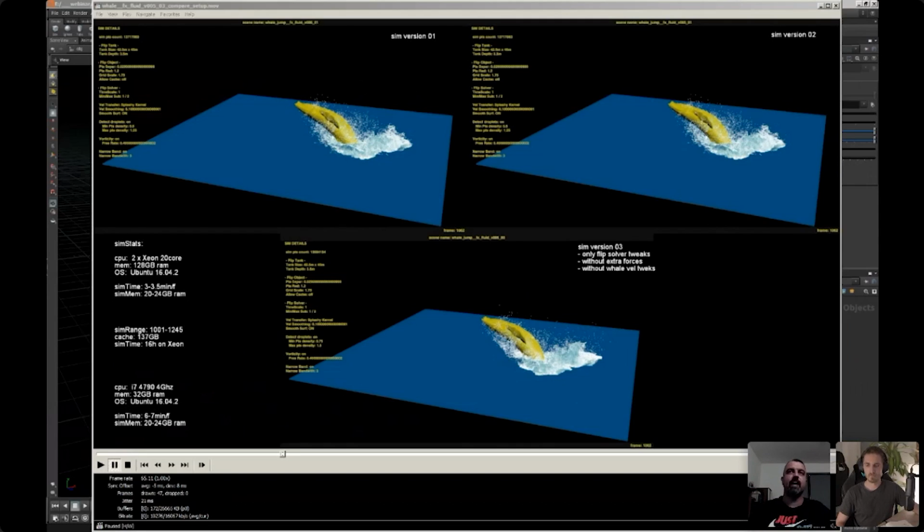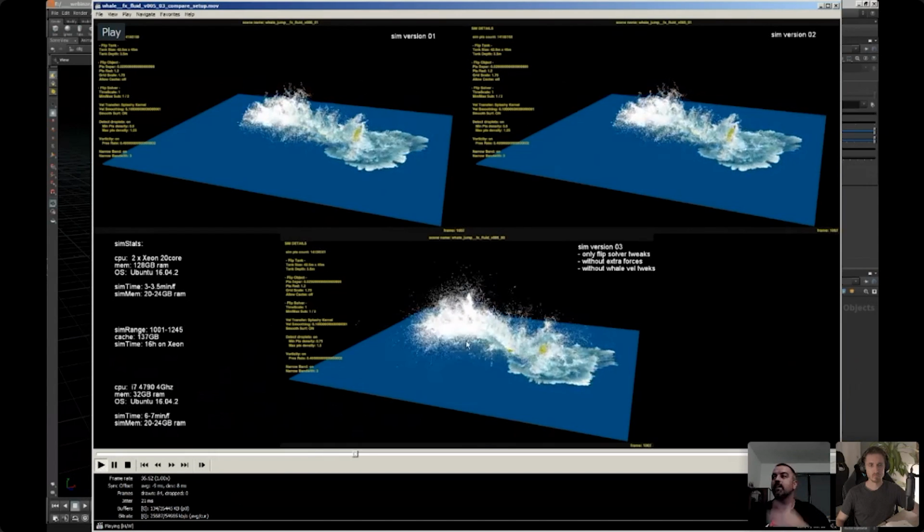Sometimes, if you want to do real water, or if it's stylized, you still have the wedges, so you can immediately say, I need a streakier splash, or velocity smooth. For example, these are the different sim versions at the end that I like to do. It's the same resolution, just with different tweaks, maybe droplets, threshold, velocity smooth, and I want to see how they work all combined.